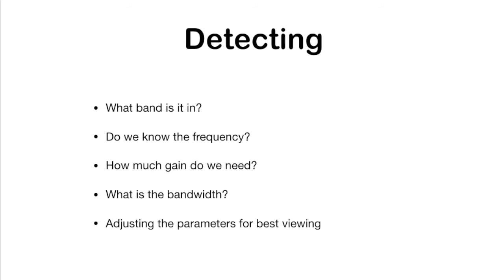With respect to the first question, we want to understand in what band the signal is in. Since we're using this remote control, and it's already said that it's in the 433 band, then we might have some indications on where the frequency is. Actually, here in the back, I can see that it's in the 433.92 megahertz frequency.